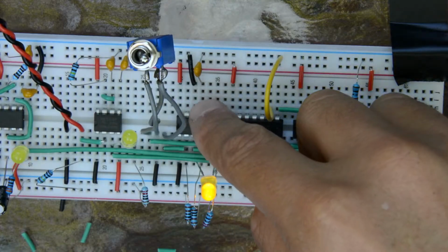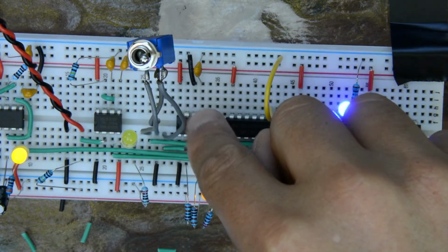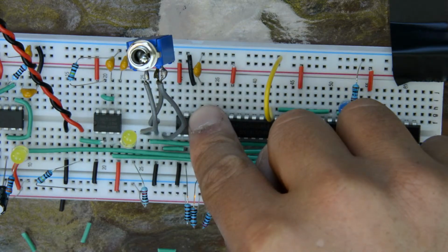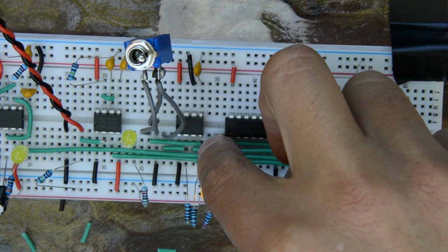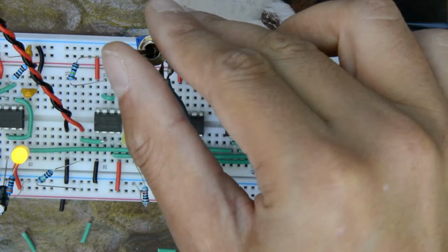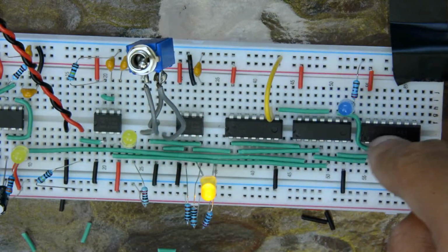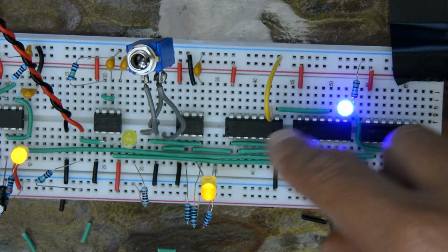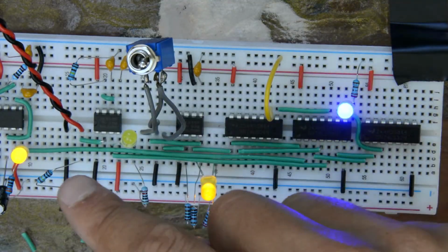This third 555 really sort of passes through all of the actual comparator logic and just uses pin 4 and I forget pin 2 to directly control the SR latch that's built into the 555. Then we have just a bunch of combinational logic to actually mux these together, basically.